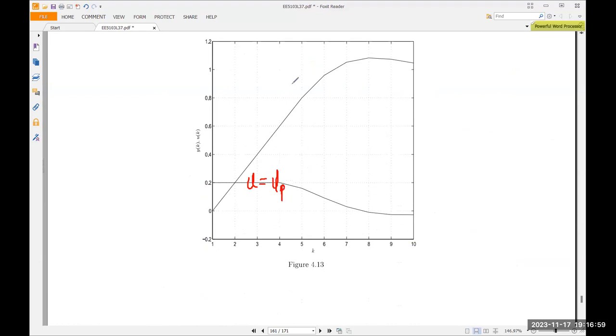Okay, this is Y. Now, if you compare, you see Y goes all the way here, set point is 1. Basically, it just crosses with a little bit of overshoot. Maybe it's an overshoot of 1.1. Then it comes back. I think if we extend, it will just go to 1 very quickly. Okay, the performance should be expected to be like that.